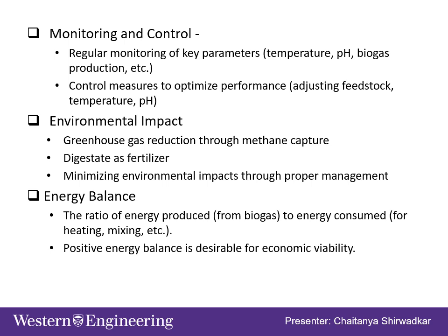To assess the economic viability of an anaerobic digester, energy balance is crucial. This measures the ratio of energy produced from the biogas to the energy consumed for operations like heating and mixing. A positive energy balance indicates the system is generating more energy than it consumes, making it economically attractive.